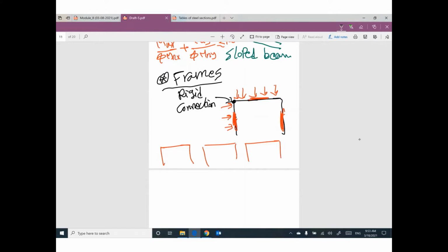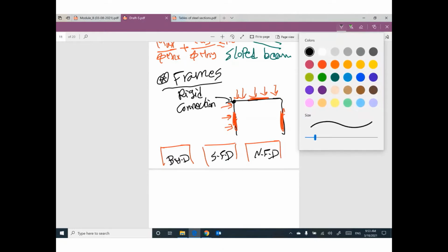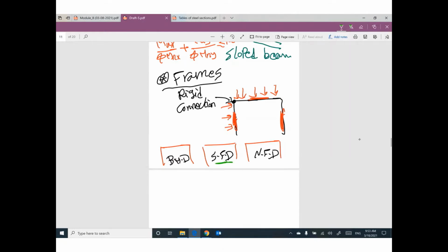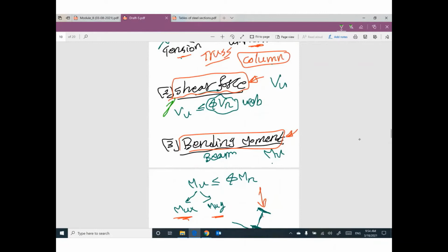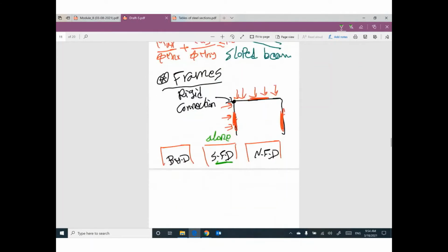So we can draw normal force diagram, shear force diagram, and the bending moment diagram. If you would like to check against shear alone, because shear is not combined with something else, we learned how to check against shear. V ultimate from this diagram. Then I can check the cross section.